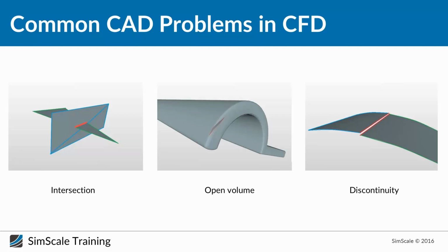So this problem can happen, and if you have this kind of problem, you will have some cells that escape inside the geometry and give you wrong results in the end. For example, imagine that this part here in reality is not empty inside, and we make it empty just because we want to do simulation.